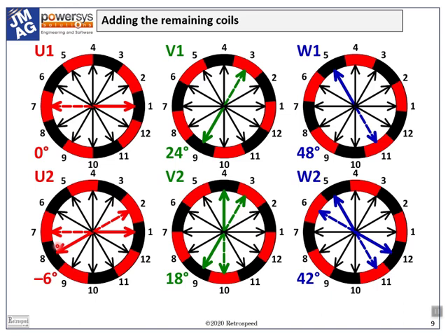We could position the rotor so that the top group are misaligned 15 electrical degrees ahead, while the bottom group are misaligned 15 degrees behind. Maybe 15 degrees of misalignment either way is tolerable if we want to connect all these coils in series.